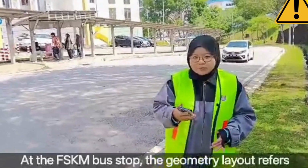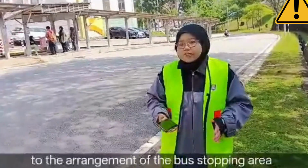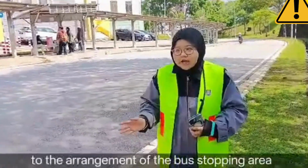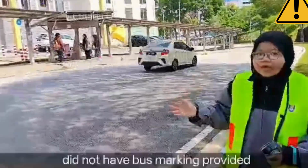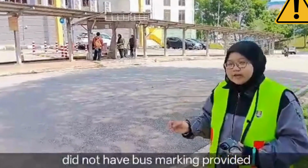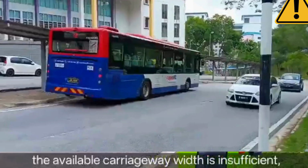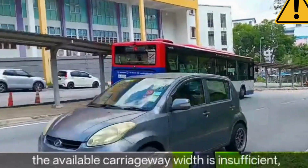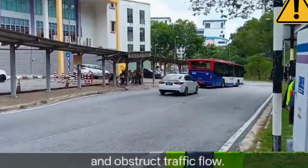Now we are at the second bus stop to conduct an assessment of the geometry layout. Geometry layout refers to the arrangement of the bus stop area to ensure safe traffic flow. We can see that the bus stop does not have any busway marking provided, and the available carriageway width is insufficient, so vehicles stop partially on the main road and obstruct the traffic flow.